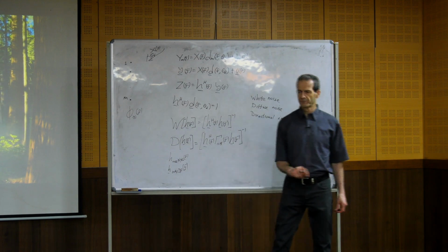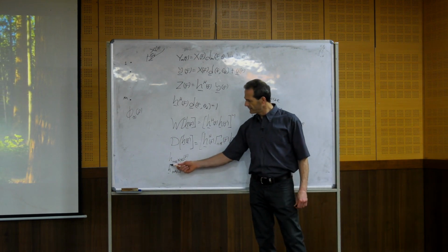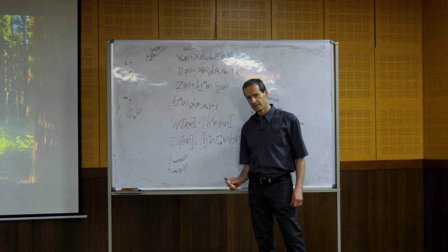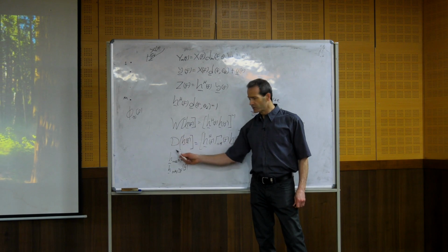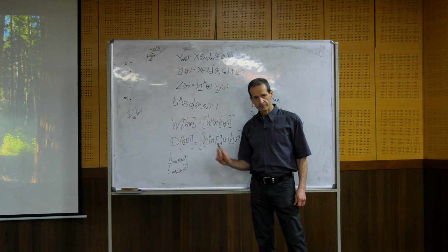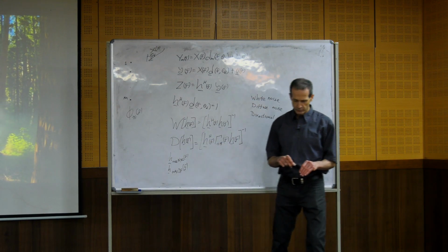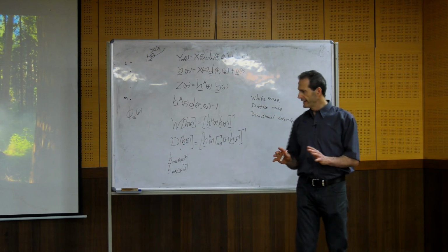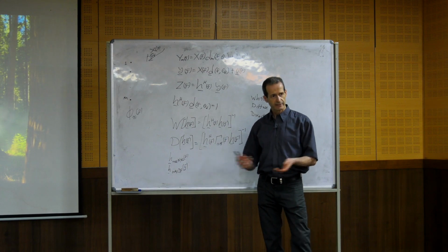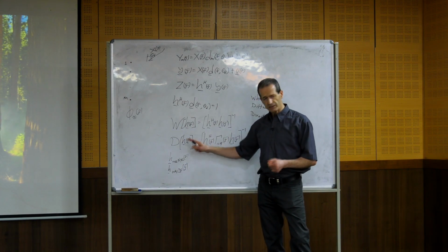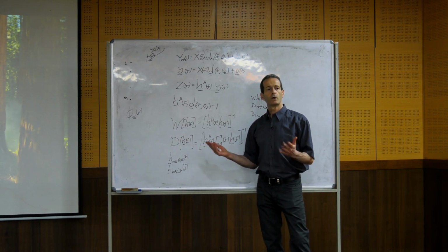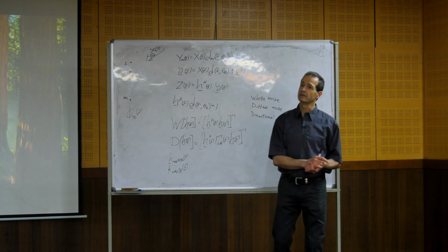Now we saw that if we design a beamformer that maximizes the white noise gain, the directivity factor that we obtain using that beamformer, so if our objective is to maximize the white noise gain, and we compute the directivity factor obtained with this beamformer, the directivity factor will always be larger than 1, larger than 0 dB.